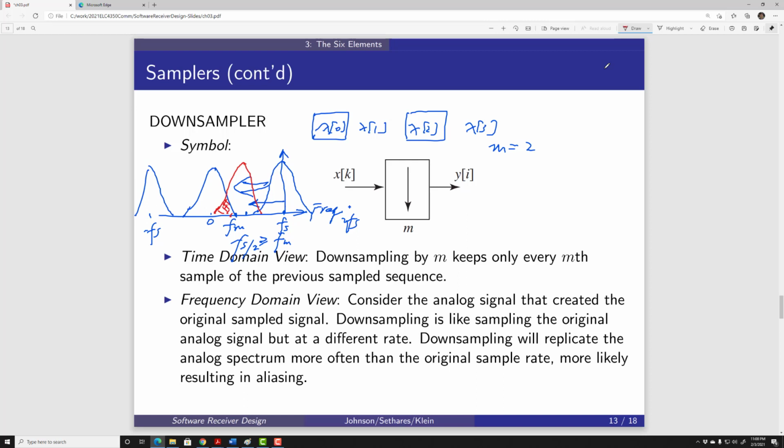Downsampling is useful if my original sampling frequency is much larger than the highest frequency in the signal. Downsampling can be used in other smart ways if you can avoid the aliasing effect, or do something to remove it. For example, there is a modern technique called sub-Nyquist sampling, which samples at a very low frequency. But because they do smart things to avoid the different copies overlapping on top of each other, they can retrieve the original information perfectly, and that is being used in modern communication receivers.